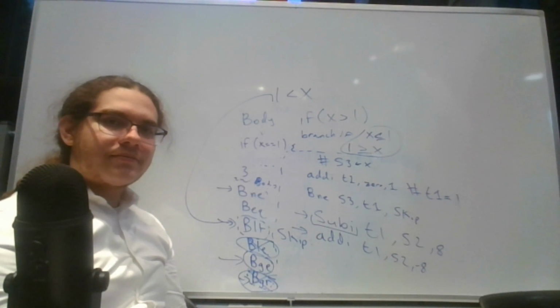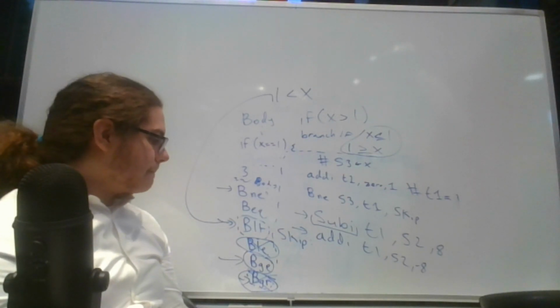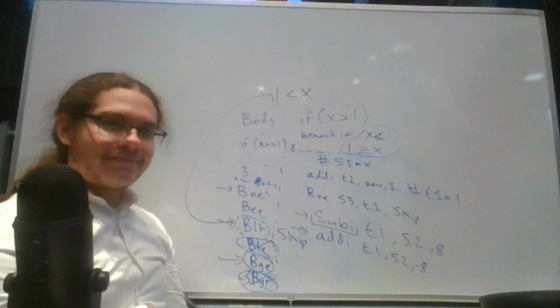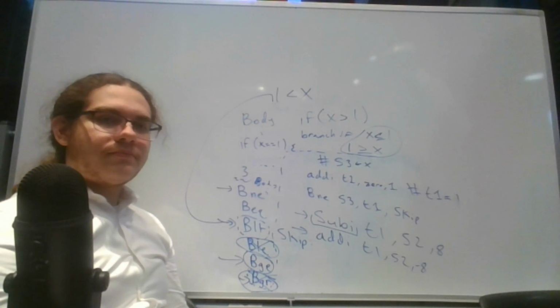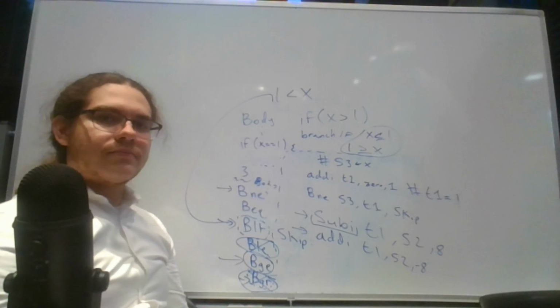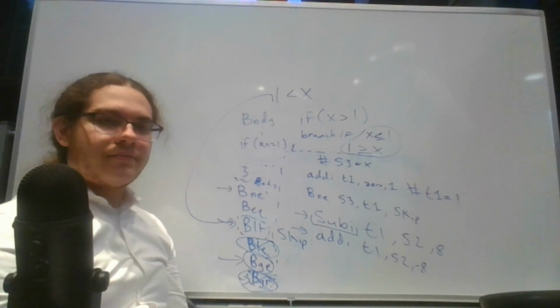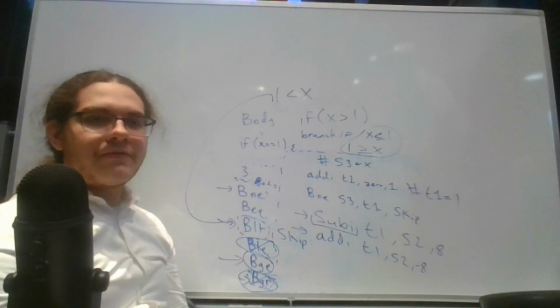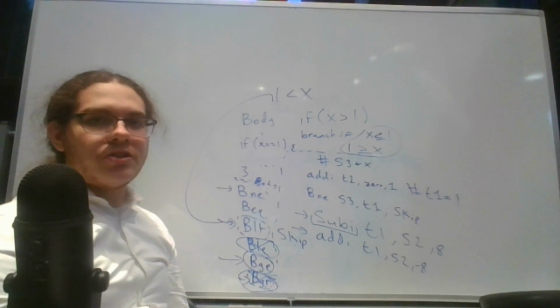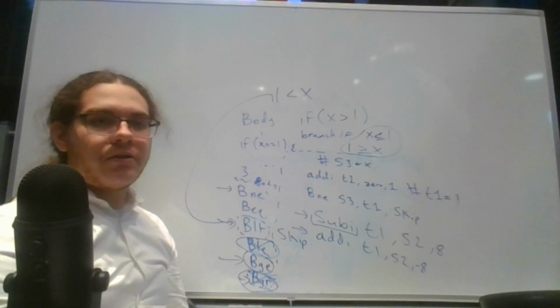Oh, no, you were explaining it really good. I was just thinking about it like how we did it with our ALU, in which we would have a signal and then we would just invert that to get, like, if it was less than we would be able to get greater than or equal to. Yeah, exactly. This is kind of like that same type of thing. Yep, exactly. We're saving out on hardware. We don't have to make a subtractor for our ALU. We could just use the adder to do both, and we just have different inputs depending on what we're trying to do. Yep.